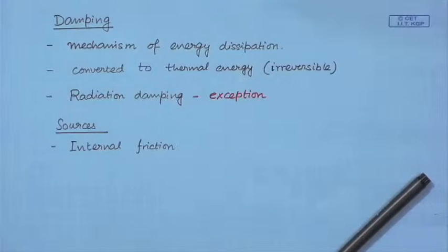Now, one thing to note is we are considering one dimensional structures. There is no question of any layer in a one dimensional structure, but then we are going to have a phenomenological model based on the rates of stretching, for example, of the structure, the rate of strain. So, strain rate is used to model internal friction or internal dissipation.